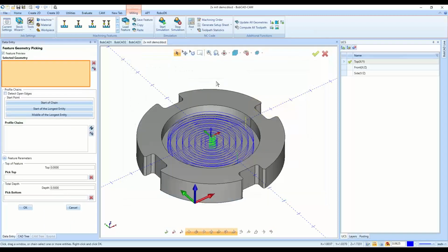Now, similar to the chain selection with wireframe for a drawing, there is a chain selection option for surface edges for programming here in the CAM portion. Instead of holding Shift and clicking on a line or an arc for chain selecting around a drawing, this would be right clicking on a surface edge, and you've got 2 options here. You've got constant Z and you've got loop selection. The easiest one is constant Z.